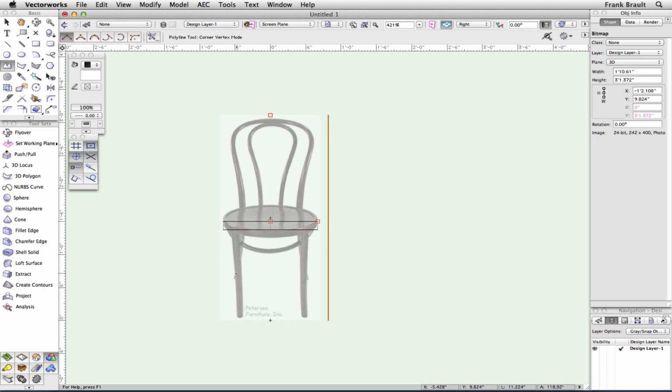So I'm going to start with this sort of curve shape for the chair back. And you can see that behind here is the curve. So I'm going to start here, and I'll stretch it down into place when I get the curve. I'm going to change this to a Bezier curve so I can work with it in place.